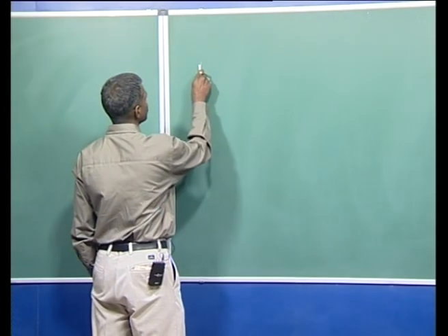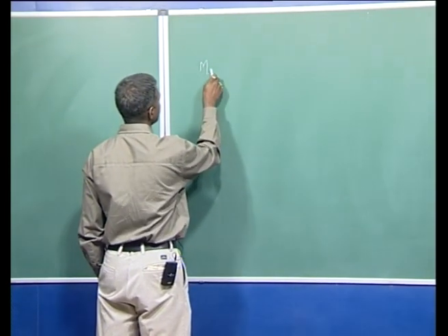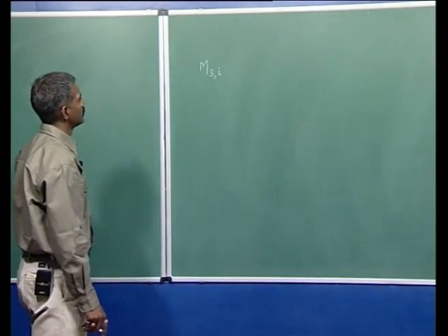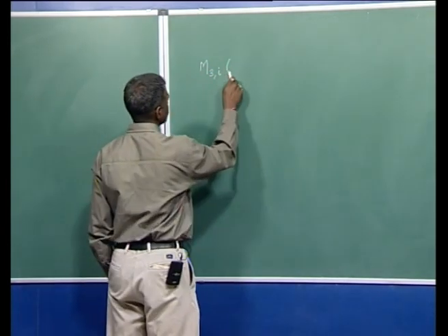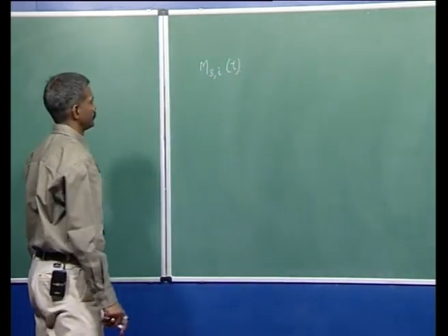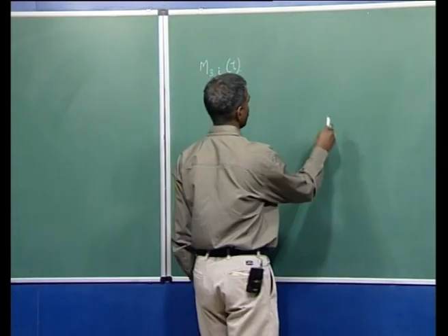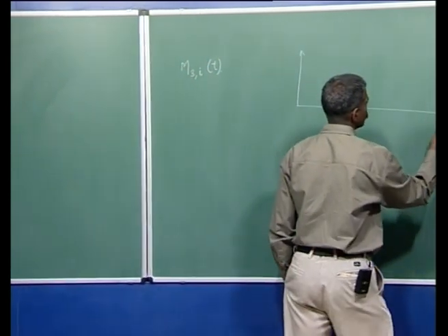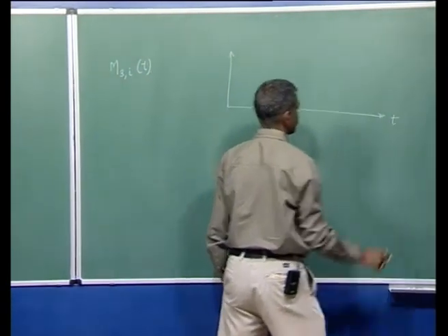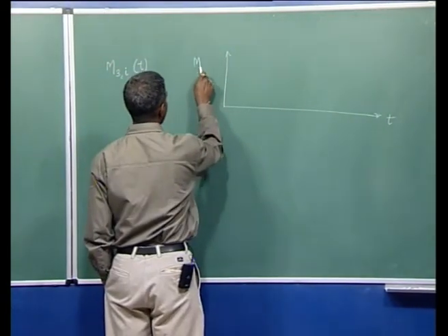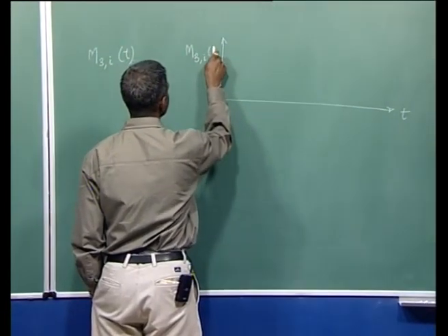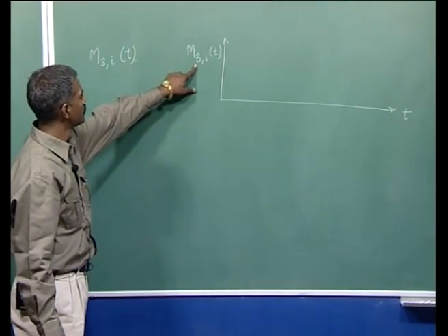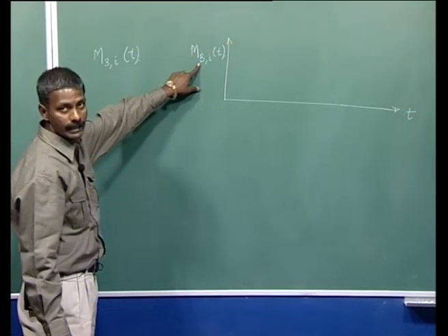How about constructing a B-spline basis function of order 3, and I would represent the last knot as a function of t. Draw the vertical axis, draw the parameter axis. This is M_3,i(t). 3 is the order of the spline. That means that the spline would be quadratic.